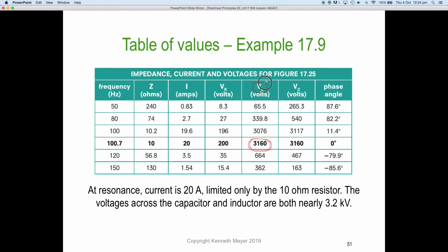So at resonance, you're going to get very high voltage across the reactive components. And you'll see it also on XC. You're going to get very high voltages across the reactances. Again, they're both exactly the same voltages because they're both the same reactance values, but at 90 degrees out from each other. Very high voltages. What's going to happen here is any capacitors there are in the circuit are probably only built to handle about 400 or 500 volts. So the capacitor is going to break down. Also, the inductors in the circuit might get insulation breakdown because of these very, very high voltages.